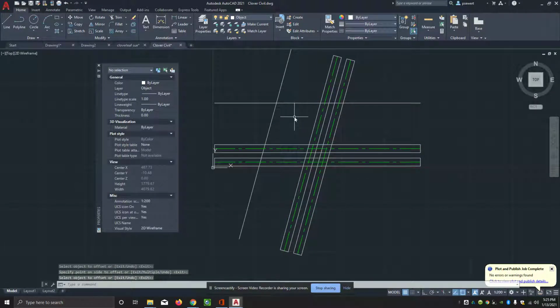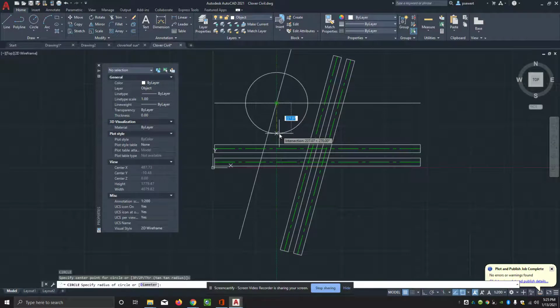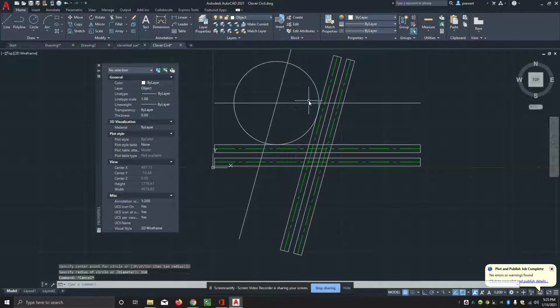Oh, you got to find the center of that. Yes. So it kind of gives me temporary construction lines that I can... And then you're just going to issue a radius of 310. Yeah, I bet you could use tangent radius there for that circle. Right. In AutoCAD, there's multiple ways of doing basically... Yeah, there's multiple ways to skin every cat, right? Right.